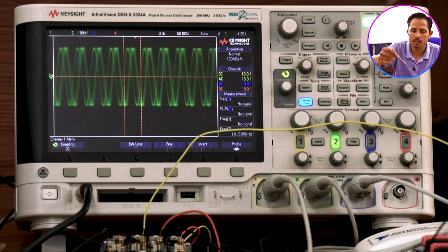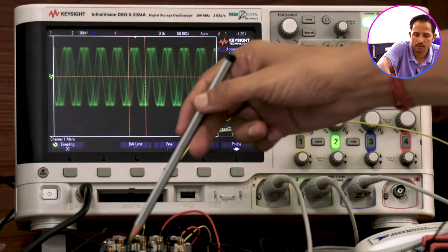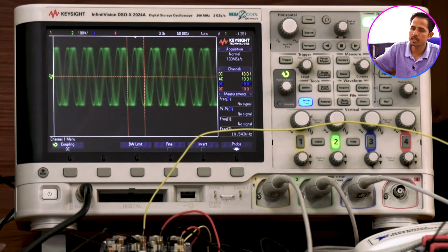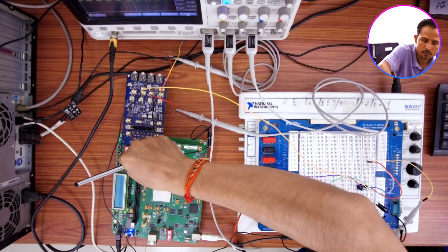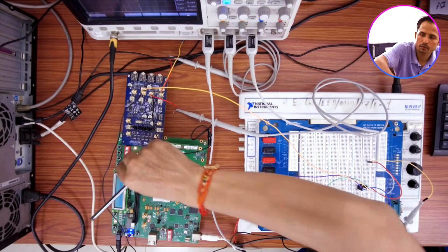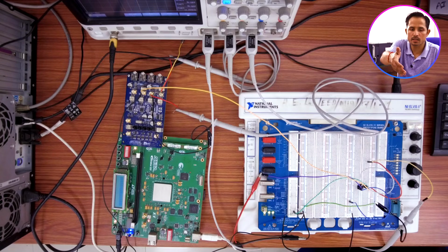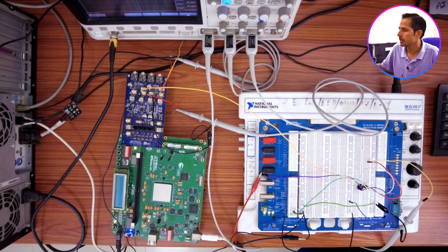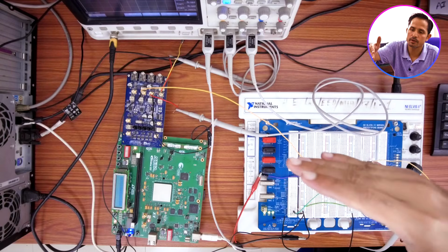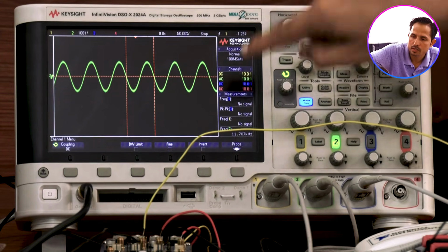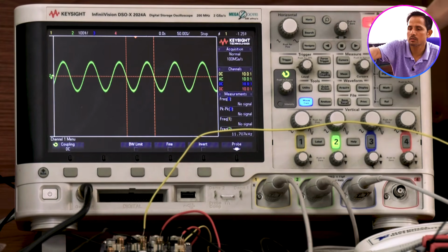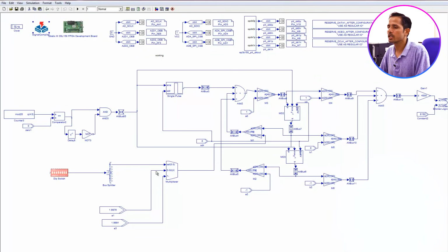As soon as I change this DIP switch from this position to the position of 1, it will be changing the frequency. So let me now select this one. So we can see, as soon as I change this DIP switch from 0 position to 1 position, it has been able to change the frequency, and it is coming around 11.7 kilohertz. So we can see properly the output has now moved from 19.53 kilohertz to 11.7 kilohertz. So this is the overall oscillator program.